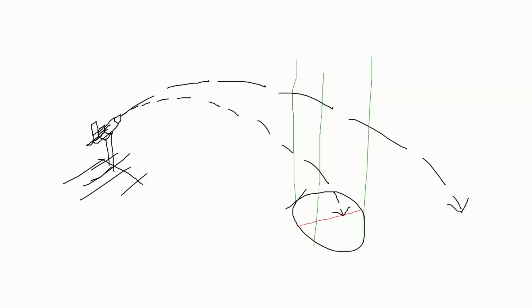But the problem with this type of system is that you will have to compute the error. Let's say the error is the distance between the missile and the target. You are going to program the controller in such a manner that it senses the error. So you will require a sensor, for example, a radar. A radar antenna will sense the distance, and that distance will be given to the system operating the controller, which will generate the error.